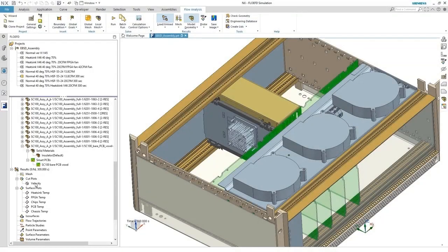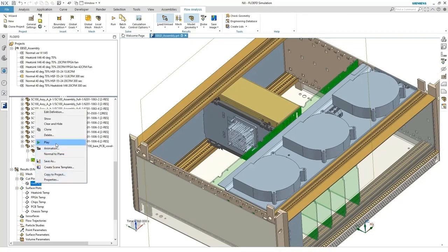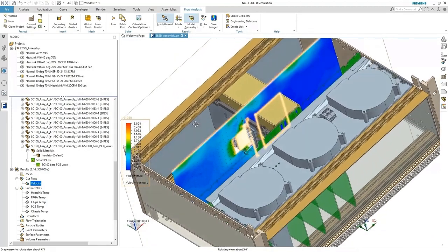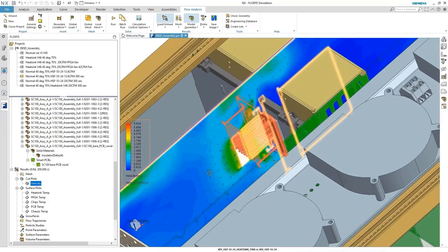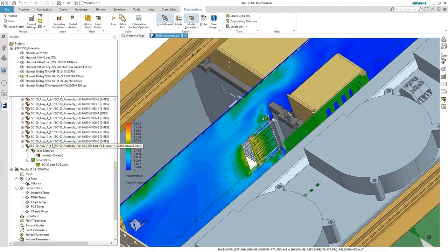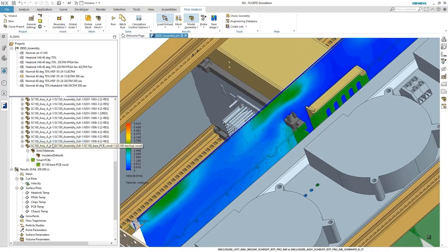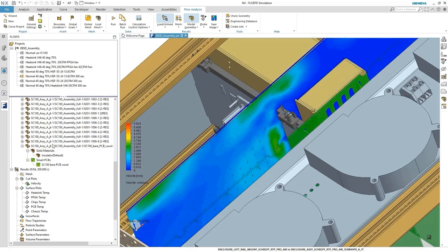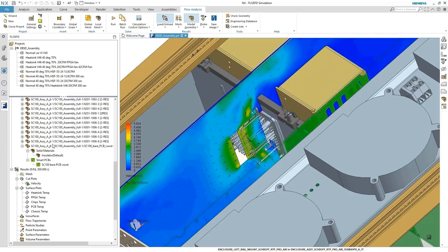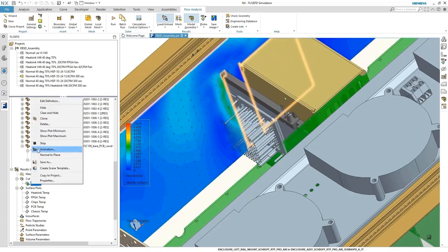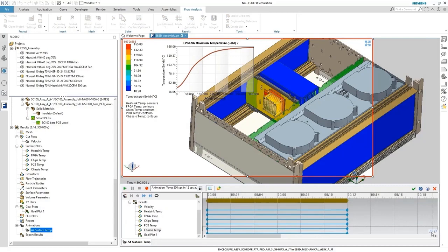Exploring the thermal characteristics of a design can be done as soon as board 3D geometry is created, not necessarily when the design is complete. Thermally relevant information, such as fan velocity, if the system has a fan, and heat sinks are considered. Running the simulation of a board within the chassis of the product makes sure that the users get the most realistic results from the simulation run.